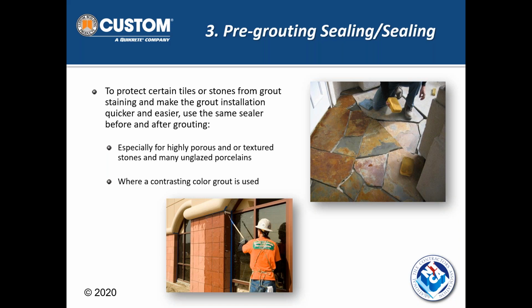There's different terminologies used, but what you don't want to do is use the cheapest inexpensive sealer you can find to pre-seal, even if it works, and then try to come back with a color enhancing sealer. It doesn't work well. I'll show you that in a minute, but bottom line is whatever sealer is going to be used, water-based, solvent-based, natural look, color enhancing, whatever sealer, topical sealer, whatever material is going to be used for that job afterwards, use that same sealer if you need to pre-seal it for the reasons we've just covered. Use that same exact sealer before grouting.